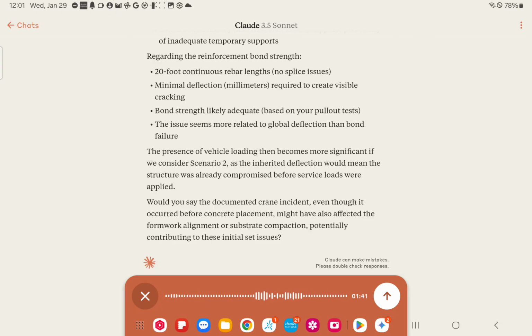Now, so they did not explore. I think they were focused more on just punching shear. That they saw the columns. Of course, the pool deck's going to pull around the columns if it's on the ground. It has no choice. Or you have buckled columns. In this case, we do not have buckled columns. The pool deck punched around each one of the columns of concern, but again, it was through first deflection in the deck and then pulling down around as it worked its way progressively over. It would fracture by the columns, and then it would be less supported on the other side, and then that in turn progressed towards the main structure of the building.